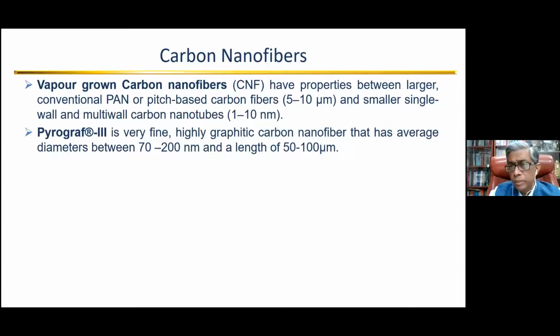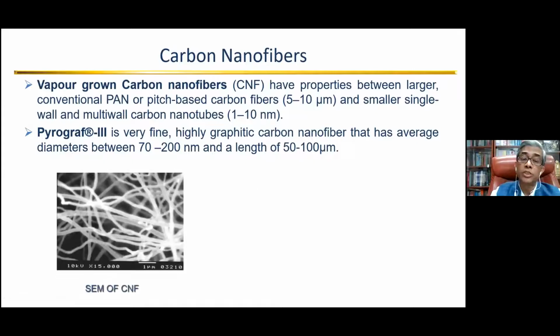Let me talk a little bit, before I come back to the clay, about nanofibers, which are also becoming very common. I talked about these vapor grown carbon nanofibers. That's what I was telling about the soot, the kajals that we are preparing. That is actually going into 1 to 10 nanometer multi-layer nanotubes. And there is a product named Pyrograf, a graphitic carbon nanofiber, which is 70 to 200 nanometer in diameter, and the length is in microns. So you can see it is multiplied by almost a 500,000 times aspect ratio.